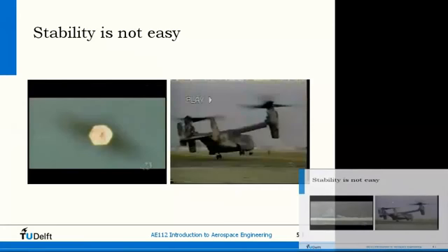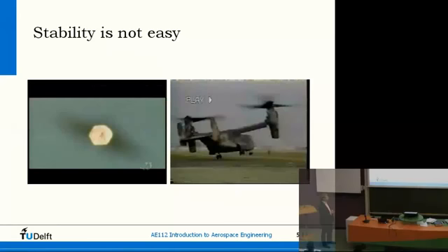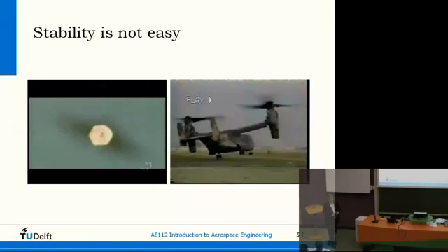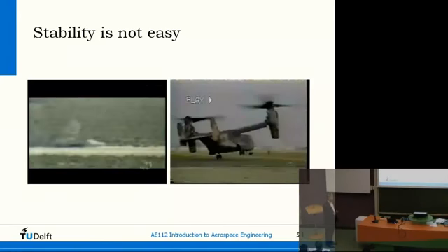Pilot unharmed. That's not what you can say about the plane. You could see that at slow speed he suddenly started diverting, and that is basically due to a pilot-induced oscillation, as they call it, PIO. Not that the pilot was doing this to get the aircraft going like that, but he just responded automatically to the deviations that the aircraft had. So the aircraft was unstable, and he tried to correct, but then overcorrected and tried to correct again, and in this way, together they formed an unstable system, pilot and aircraft.